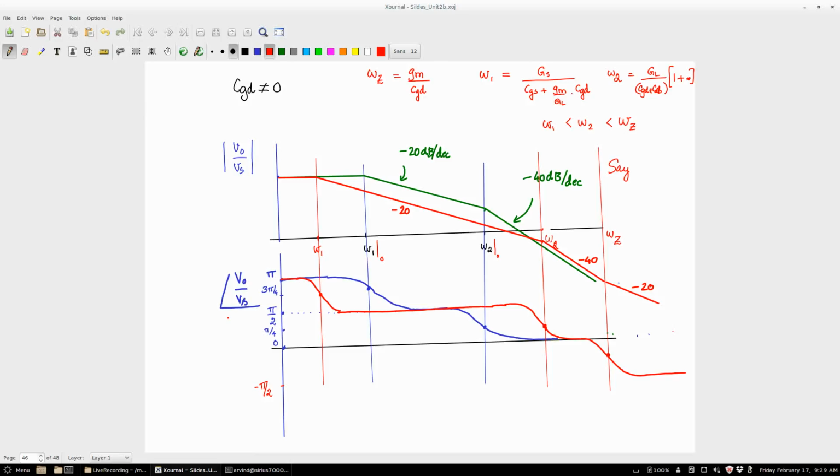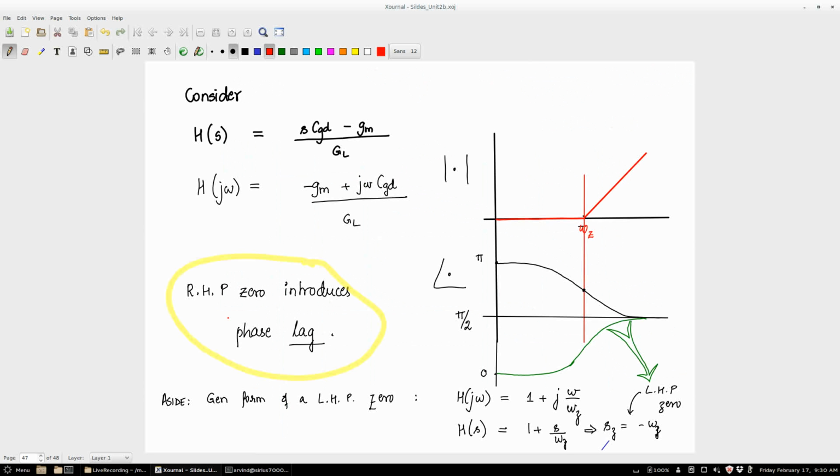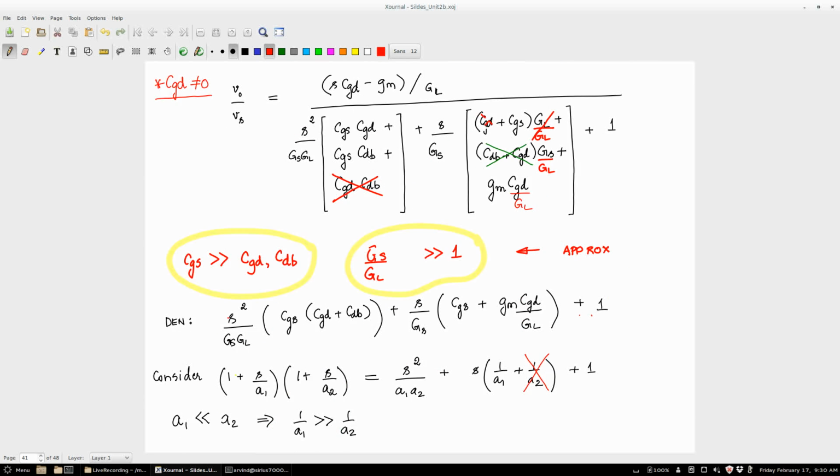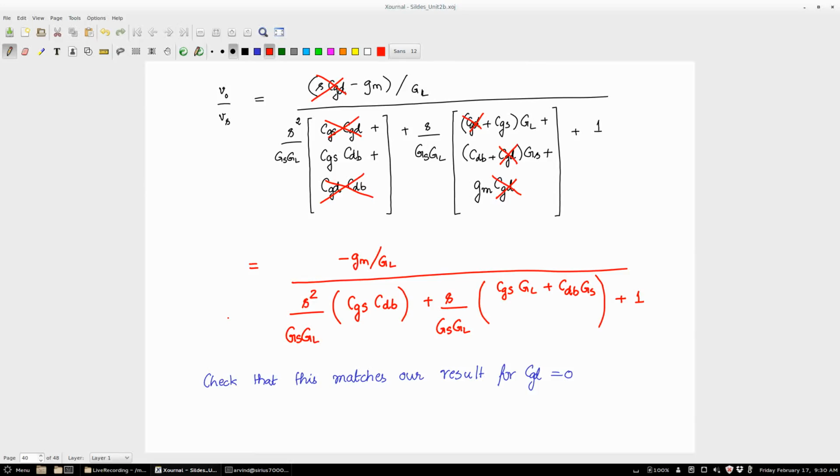Let me not confuse you now, but it's very important to know, when the gain becomes 1, what is the phase. So if at gain 1 the phase difference becomes 180 degrees, effectively you have a system where something has got flipped. Right? So there is a thing regarding stability and how that plays into all of this. That's why I am saying you should know about poles and zeros and how these things look. You will do it again in detail in your control systems class, but before that I think it's important that you know this. Okay, so go and practice this. Alright, now